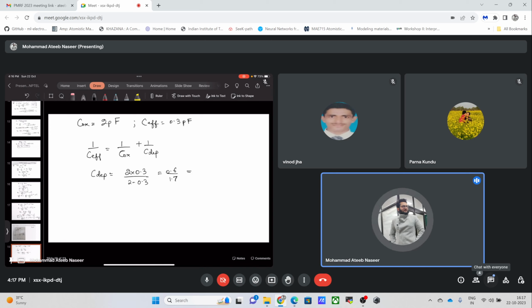We can say this psi s is equal to, not 2 phi f, which will be the strong inversion. Since this is the start of the inversion, the surface potential is building up, and it is equal to phi f. So it would simply be given by kT times ln of the acceptor doping divided by the intrinsic concentration, its logarithm.